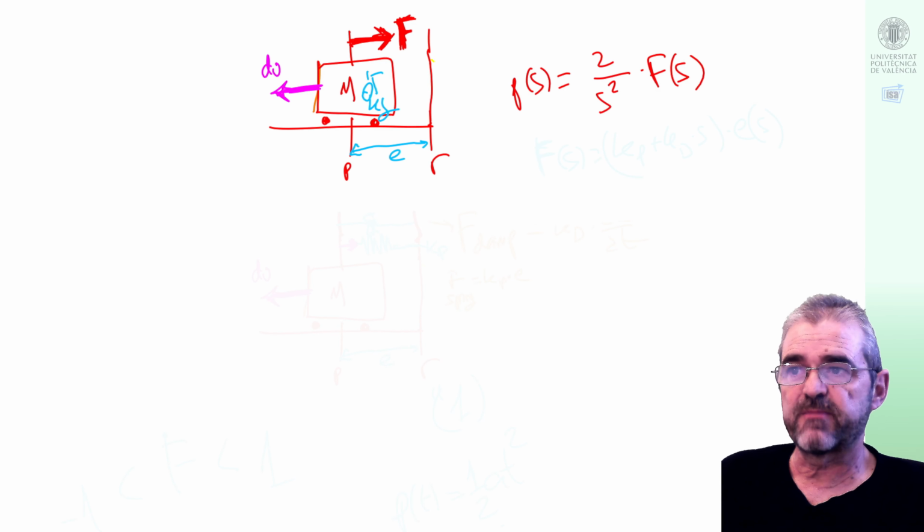Our double integrator plant modeled a half a kilogram mass to which I could apply an arbitrary force, capital F. We thought that friction was negligible or it was suitably compensated. If based on speed, I can compute an approximation of friction forces so that I can apply them in the opposite sense. So in that situation, my transfer function was 2 over s squared.